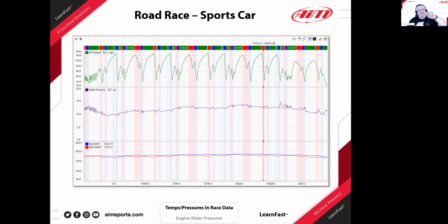And number two, I put the temperature sensor right at almost the highest level of the motor, as the water is going back into the motor. And as soon as it started to lose water, the water temperature sensor was out of the water and just in free air. And one of the biggest things I've helped a lot of people with is understand, boy, a fairly inexpensive water pressure sensor